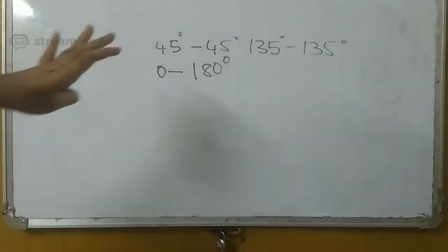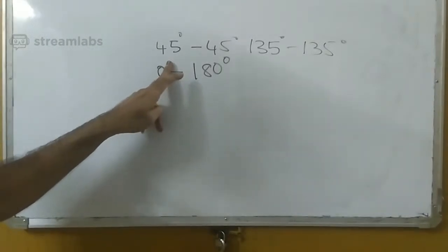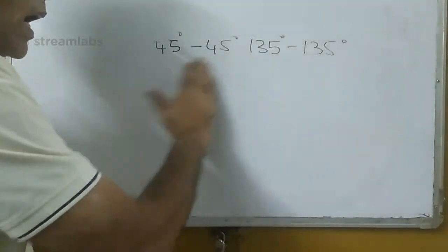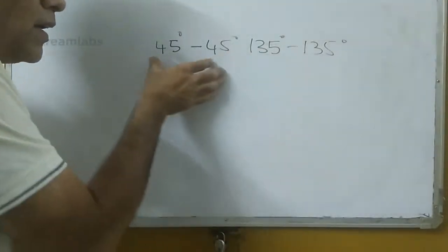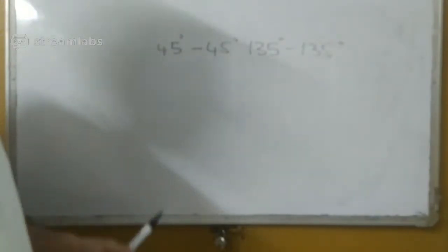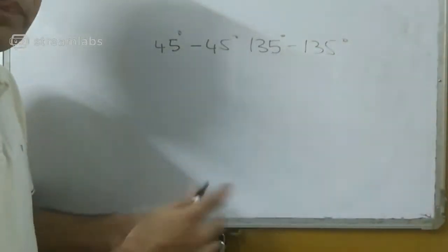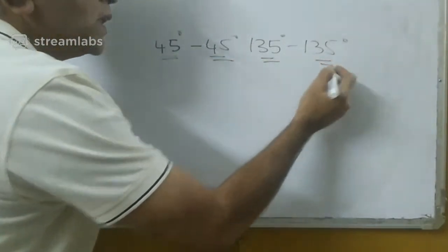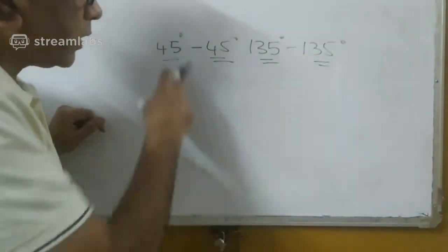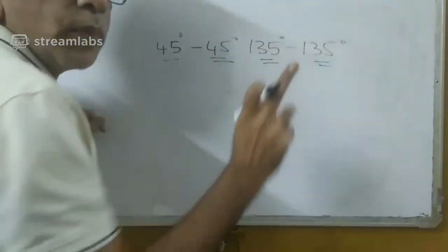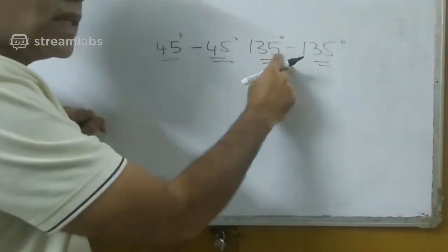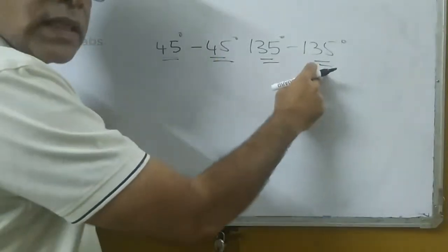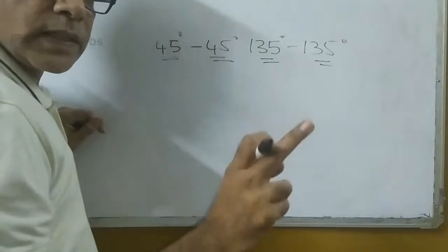Which will now help me to increase the number of bits per signal element. Now see, when I have 4 levels of signal, in PSK, you can call it multi-level PSK, if I have an option of generating a signal with more phases, this will help me represent more bits per signal element. Now see how many phases are there? 4 phases. How many bits can I represent? The 4 phases are my signal elements; phase is the signal element in PSK.